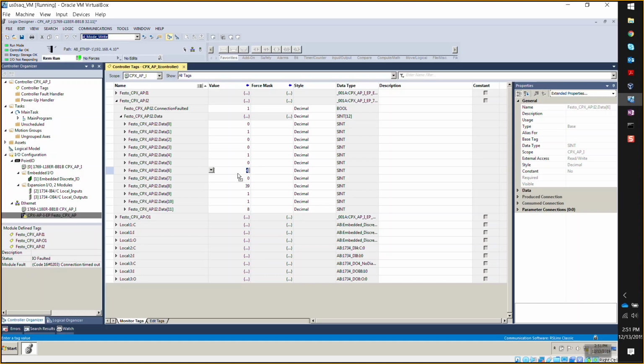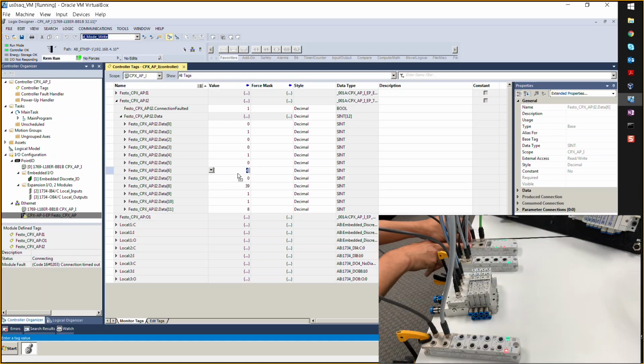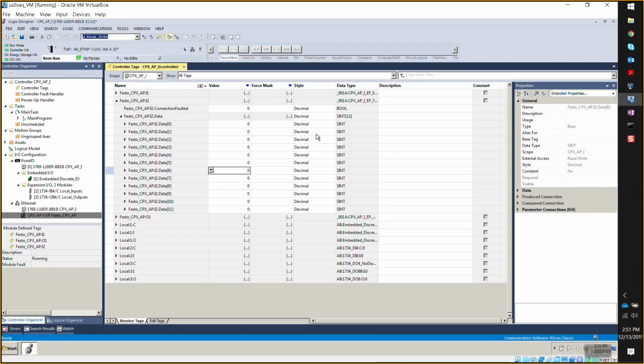Okay. So this is an example. These are examples of a basic setup for the API system with Ethernet IP. But we have one additional feature in here that I think is very important, and it has to do with doing parameterization, which may not come up in every case, but if you have more advanced modules, or even for this example without just simple outputs, if you wanted to hold last state, that's a parameter that you need to set. We have a nice new way of doing that here, and it's called using our L5X export function.